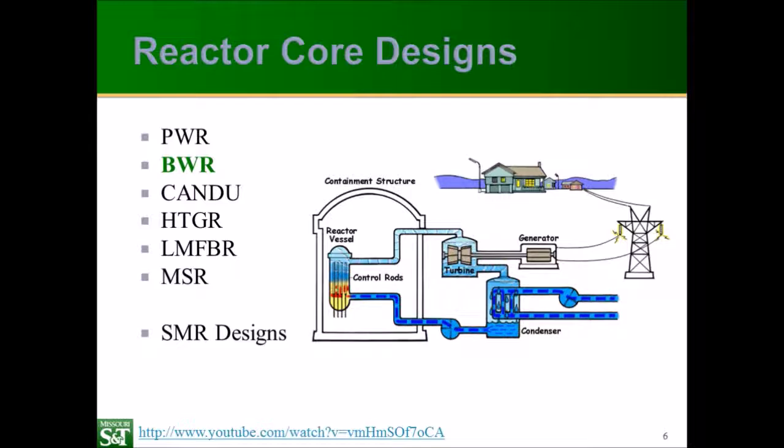However, it means we have radioactive contamination of the steam running through the turbine and the condenser, so those systems have to be shielded to protect the personnel. It also helps that the flow requirement through the core during an accident is quite low. Because of the boiling, that heat transfer is very effective, so we can maintain cooling even at very low flow rates.